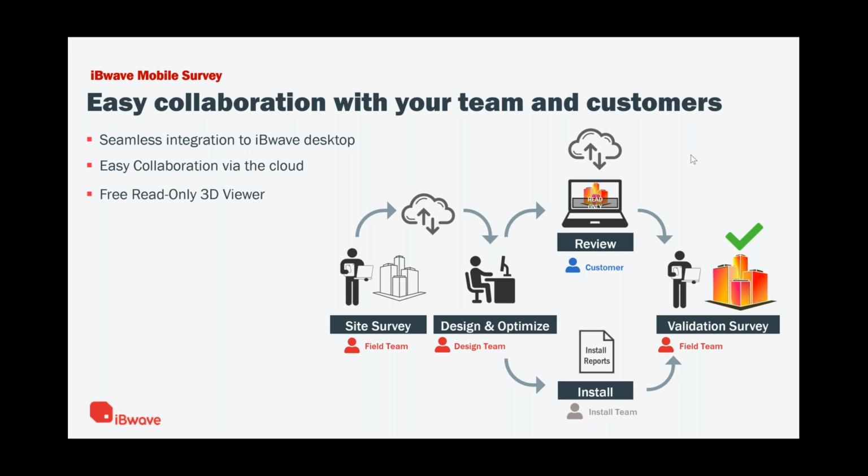Once the designer completes the assessment or the design for the building, it can be shared with the customer for review and approval. iBwave provides a free viewer app to allow the customer to open and view the project file and check the report and prediction. However, the viewer software doesn't allow any changes to the project file. Once the customer approves the design, the file can be shared with the installation team for deployment. After the installation is done, the acceptance team can download the latest as-built and report and validate it on site.